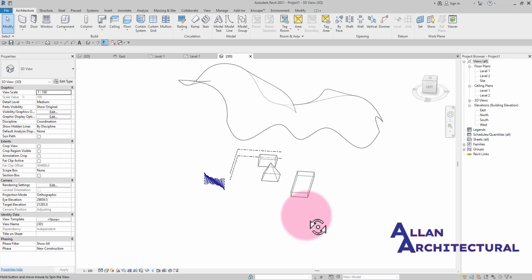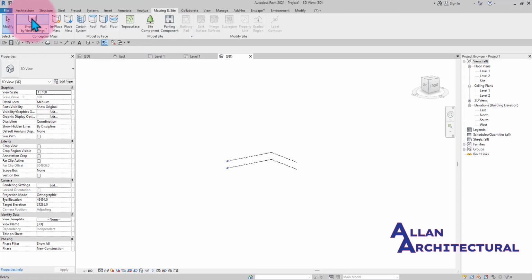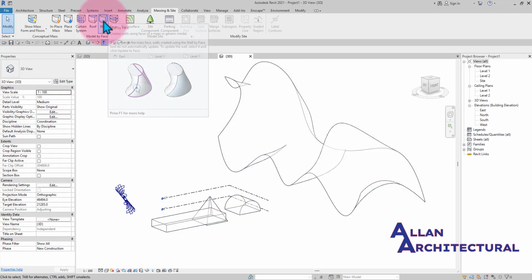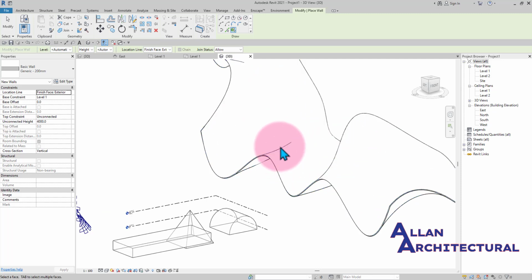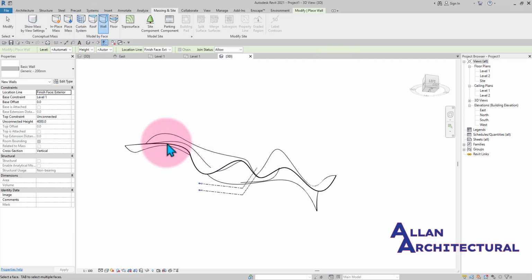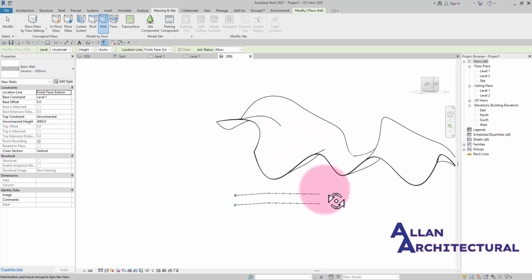So this is how you can actually load this in there, and you can go straight into your massing and site, and you notice in here it's turned on, and when I turn this back on, it's now visible. When I turn this off, it's all not going to be visible. So we need to update the phases to whatever parameters we are going to be using in here, or we can click on our wall and apply it to this, and Revit is going to update that with the wall. If I go back in here to mass and site, show mass, you notice that this is now visible even when the mass is off. Even when I've still turned off that mass.